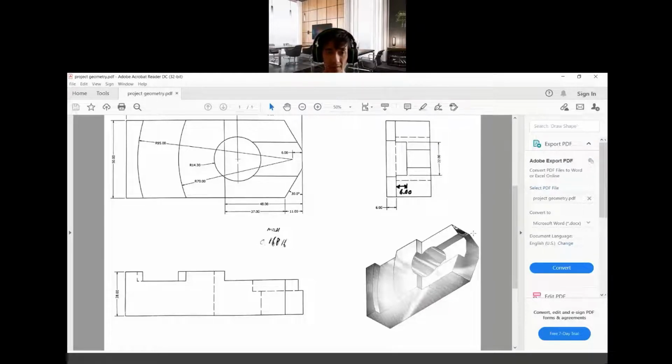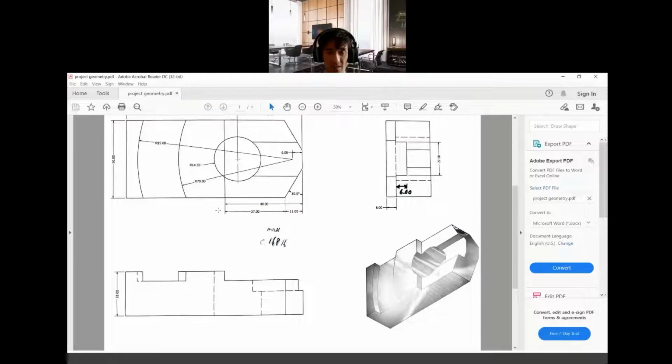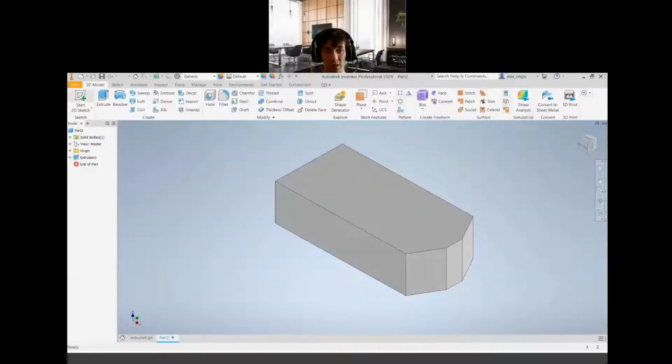So that we can cut through this extrude cut till here, the distance 48 here, from this top surface, this front surface here. Okay, so you will see that sketch. Now we go to 2D sketch again. So again, I would like to stress to you, don't go to 3D sketch. It's 2D sketch only. Go to 2D sketch.